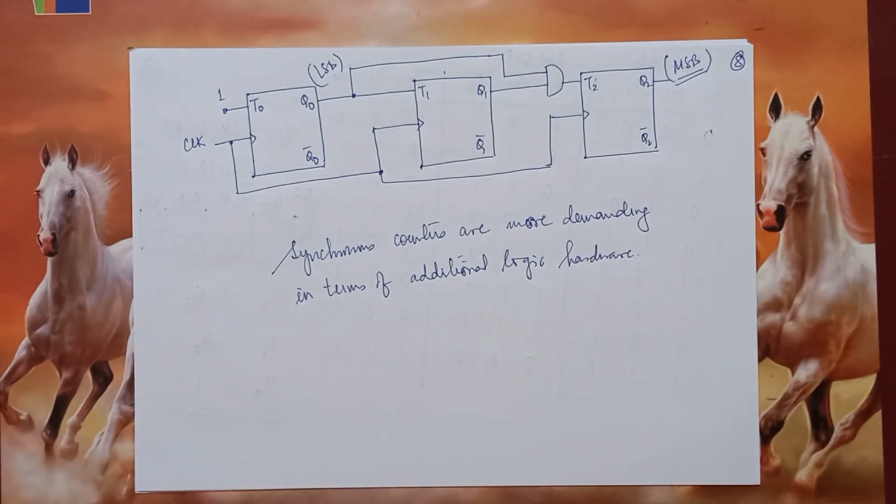So in this particular lecture, we saw how to work with asynchronous circuits to get the counting up to a particular value that we want, which is not necessarily the last counting value. We saw how to use positive edge triggered and negative edge triggered flip-flops in different ways to get counting sequences. We saw what is an up counter and a down counter. And thereafter, we established the drawbacks of asynchronous counters, and we moved over to something called synchronous counters.